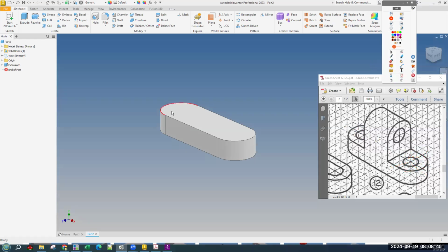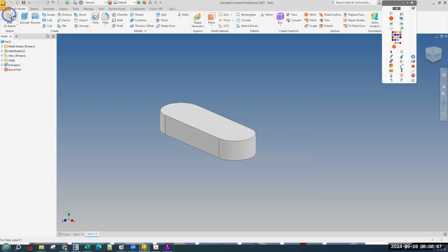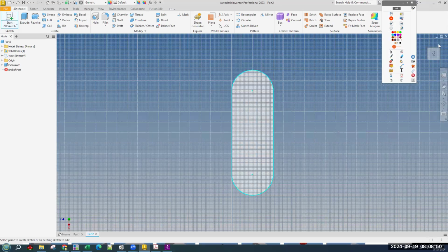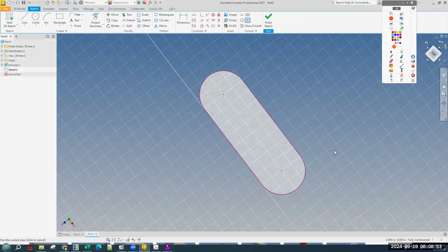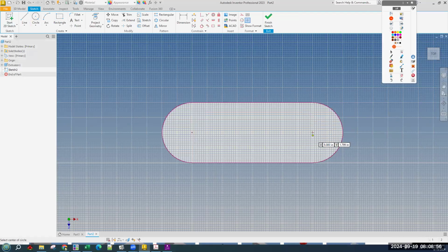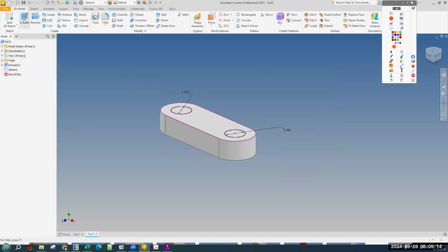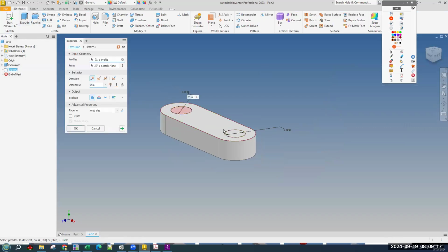So when we go to sketch on this surface, we will get snaps or projected points that we can snap to automatically. So we just need one circle that's here and another one that's here. And dimension, these are both diameter 2. And we'll finish sketch, extrude, choose each of these and only those, and switch to cut through all, hit OK.